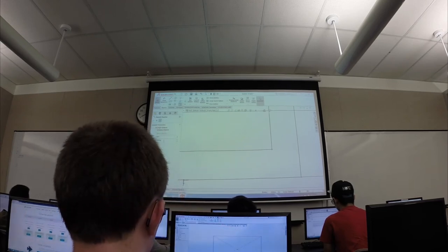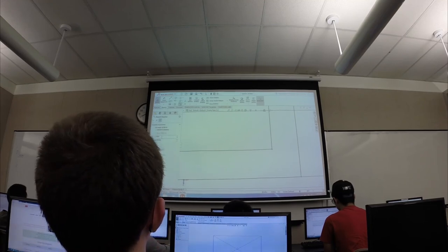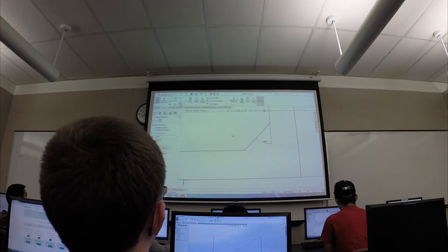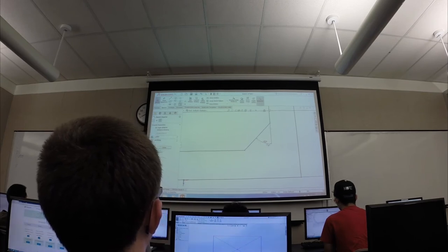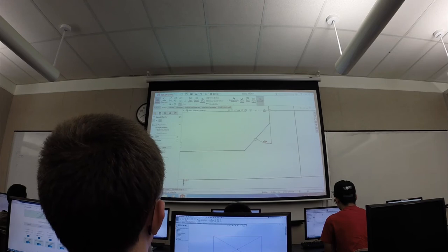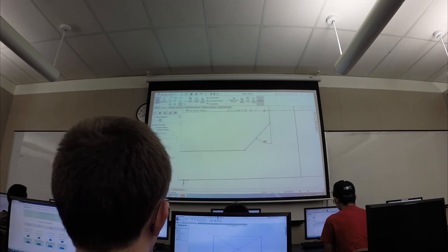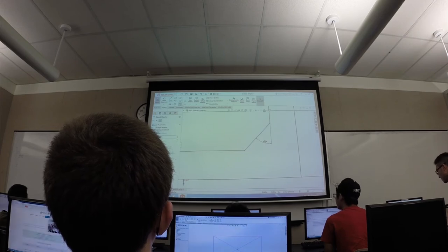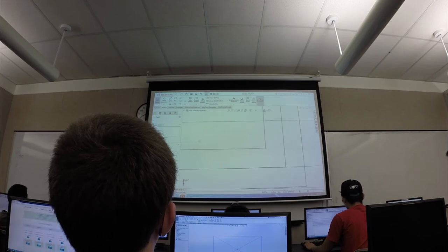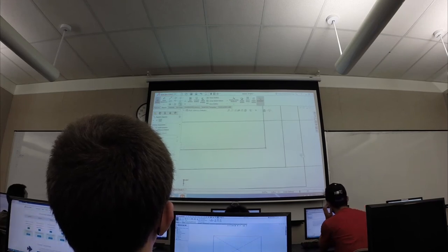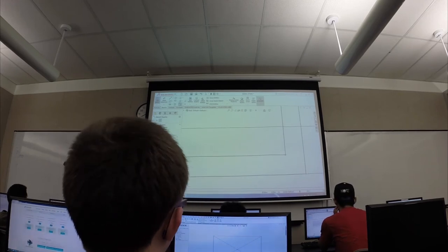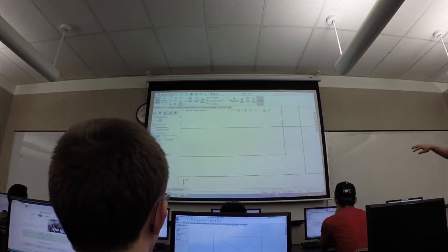So we're going to try this one. We're going to do 45 degrees. We're going to say, okay, we want a 1 inch long chamfer. Boom. And it does that, right? You can see that it returns, okay, this is a 45 degree reference from that vertical line. We're going to change that. So when you're doing an angle distance relation, if you were to keep it at 45, if you were to change the length of your chamfer,